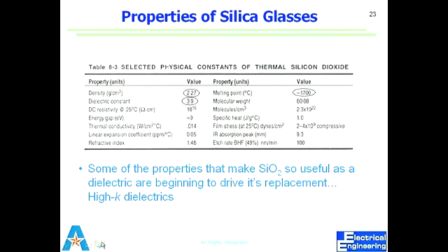Of course, we don't normally remove the whole thing. After lithography, we remove it from wherever we have made our openings. So if your chart says it's 2000 angstrom, you do 2 minutes 30 seconds, slightly above. Generally it's 10% above the time. So if it's 2 minutes, 120 seconds, you do 12 seconds extra, right? I would do 2 minutes 30 seconds to completely etch silicon dioxide.